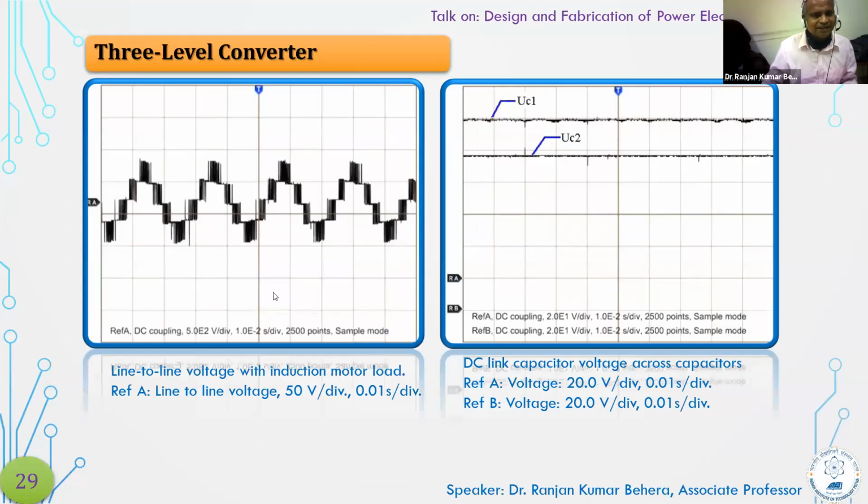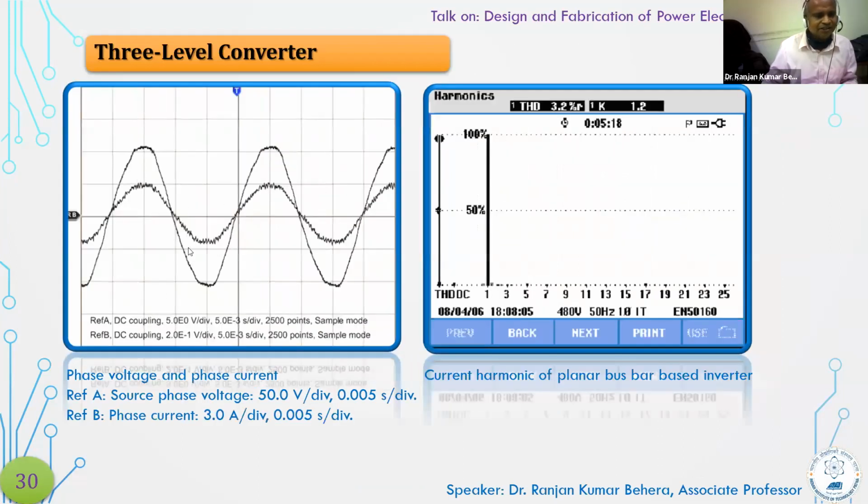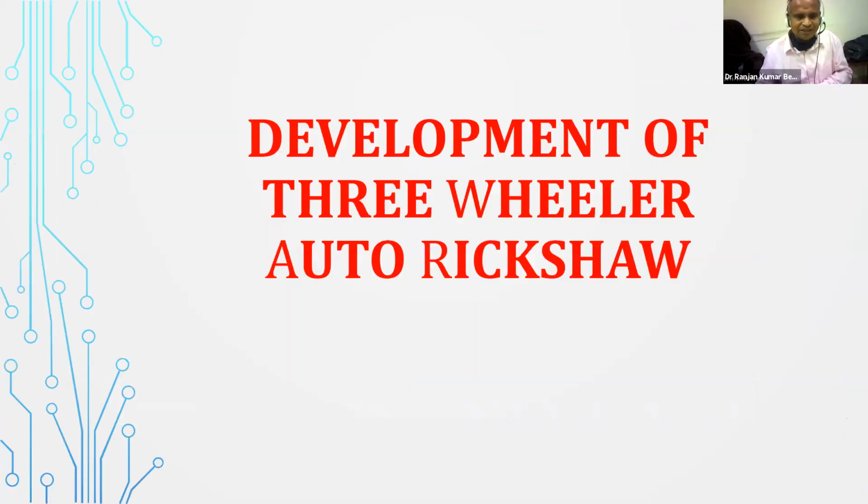And then you can see both voltage and current are in phase and they are at unity power factor. This means VI cos phi is equal to 1, cos phi is 1, and in power electronics this is nothing but the displacement factor and distortion factor. When you multiply them, that is the power factor. So we maintain nearly unity power factor.